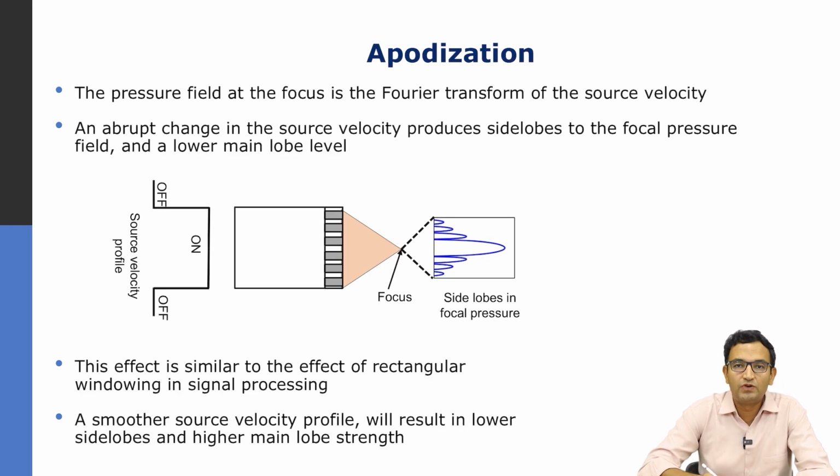A sinc function has a main lobe which is good, but it also has side lobes which will be problematic from the point of view of imaging. So, what if we could shape the aperture in such a way that we would reduce the side lobes? It will be impossible to completely eliminate the side lobes given the finite aperture of our transducer. Given the finite aperture, we cannot focus just to a point, but it will be diffraction limited focusing. So, if there was a way to actually shape the geometry of this aperture in such a way that it would only have a main lobe and reduce side lobes, that would be beneficial.